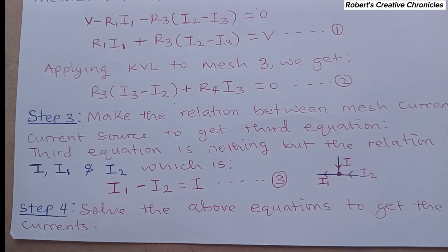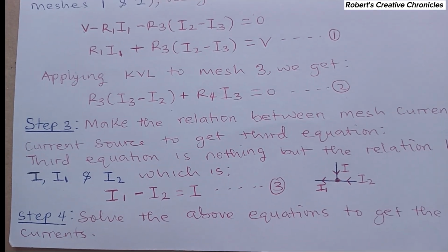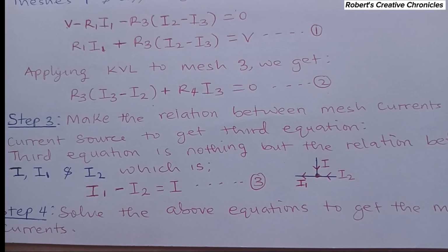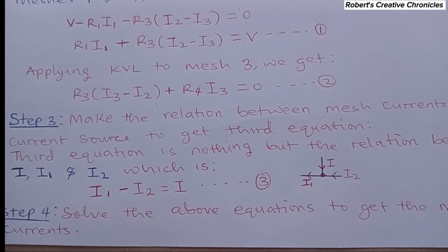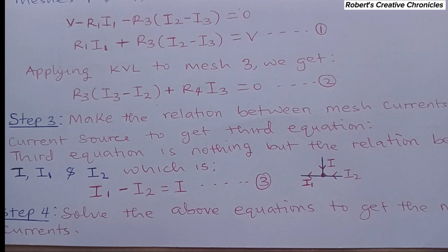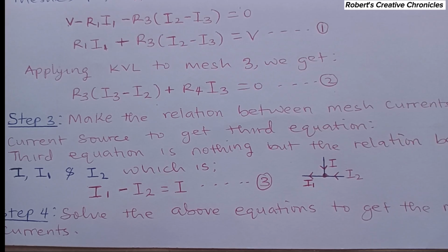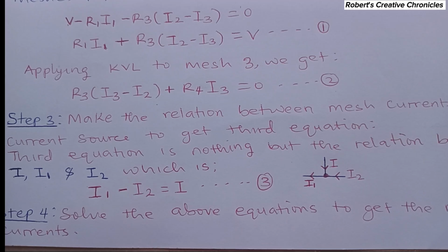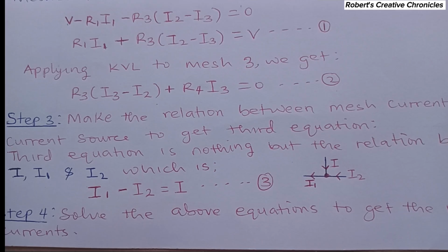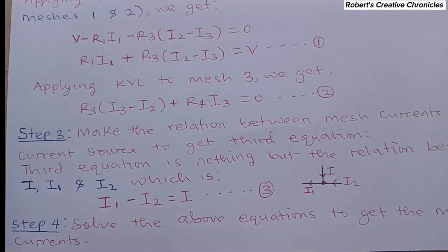Then the last step: solve the above equations to get the mesh currents. So you solve the simultaneous equations using any method you want, whether substitution, elimination, or Cramer's rule. Any one, you can solve it to get the mesh currents.